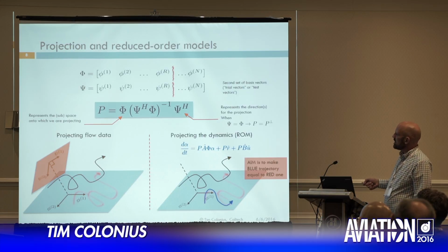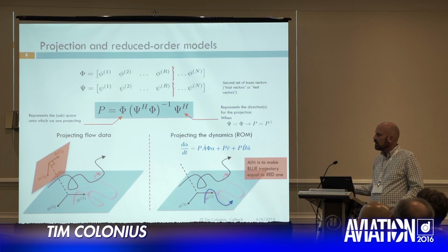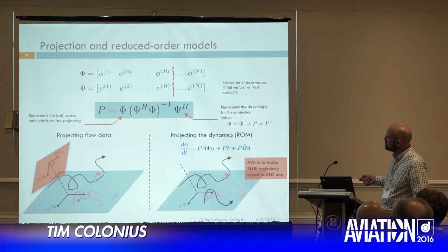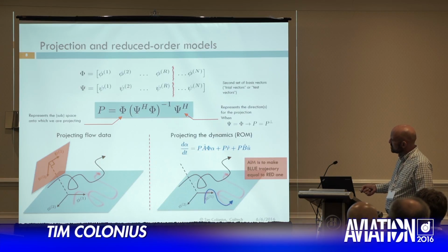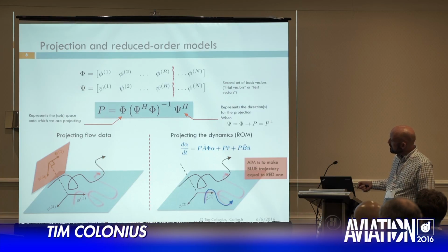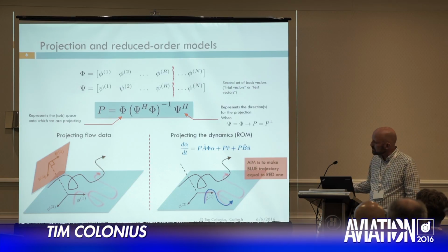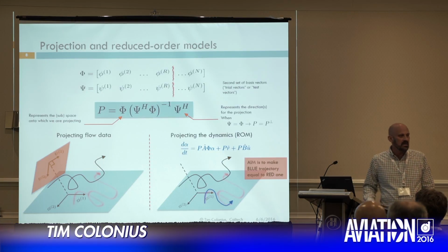And what's important to distinguish at the outset is that we often are interested in a model for the dynamics of these first few R modes of the flow field. So we can also project the whole governing equation onto this subspace. We can project the dynamics, as it were. So here's the equation for how the modal coefficients vary in time according to a reduced model where I'm projecting onto the subspace. But the aim here would be to make the trajectory, the solution of the blue system here, to be exactly the same as what the natural flow would be projected in this space, so the red curve. But as it turns out, it's not always possible, and it's certainly not easy to make the blue curve exactly align with the red curve.